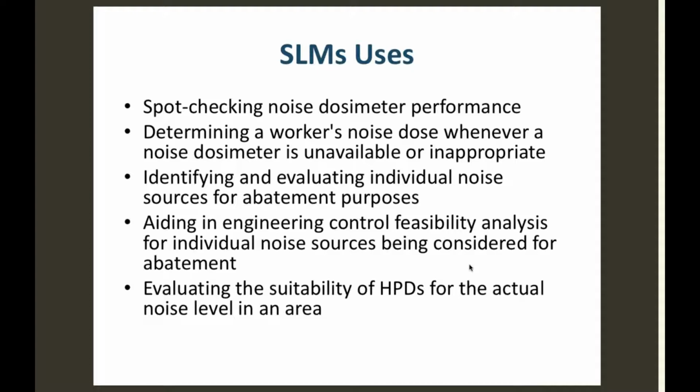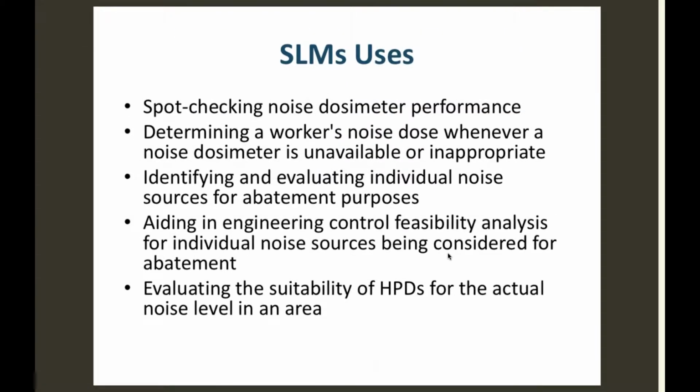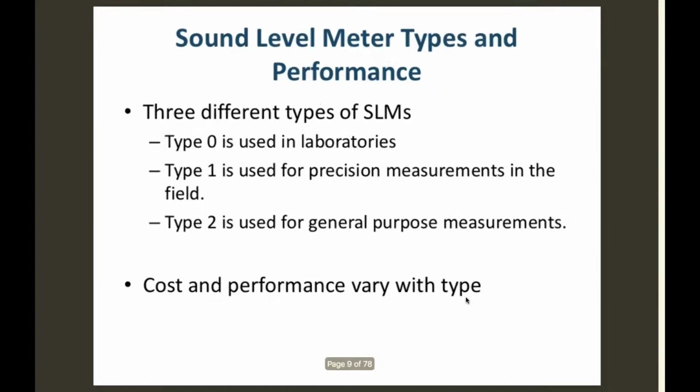Also for evaluating individual noise sources to decide which ones you have to control. In other words, in the work area, if this one is making a lot of noise and this one is tolerable, you might be able to figure out ways to move them around or locate them, to engineer the area so that you don't have areas that exceed the permissible exposure limit. Aid in engineering controls, to decide which ones need enclosures and so on. So it's basically like a survey device for the most part. Yes.